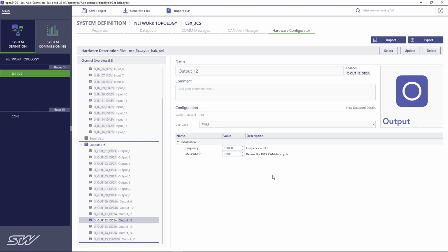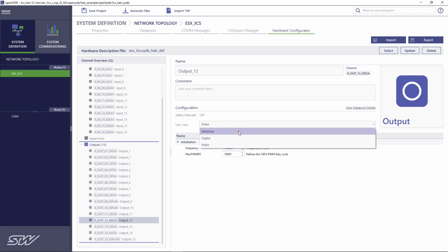However, we see with the outputs that no concrete values can be configured, for example, an output voltage or duty cycle. For safety reasons, this should not be done via generated code, but is reserved for concrete programming in the application. This minimizes the risk of accidentally setting high voltages or currents at an output.